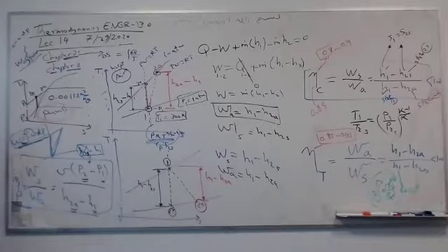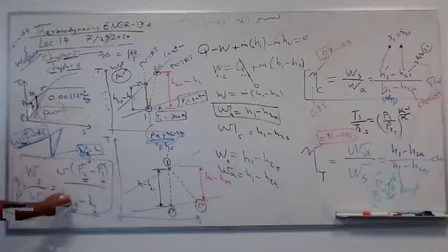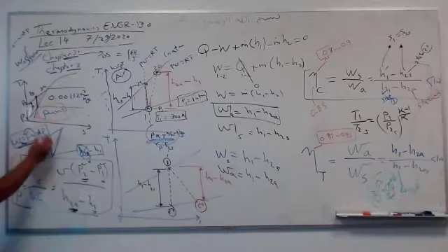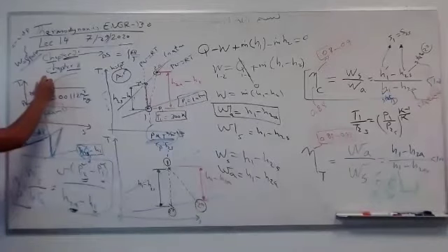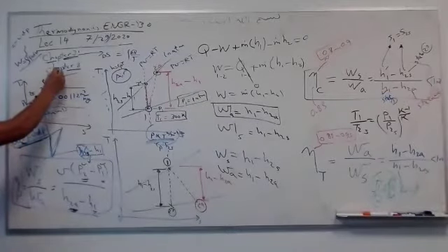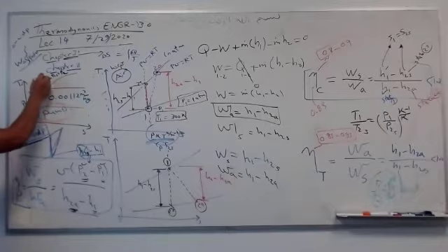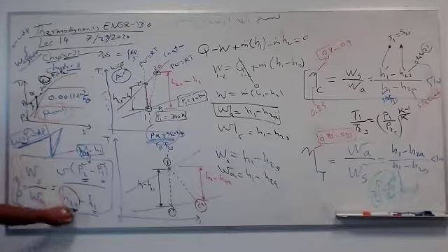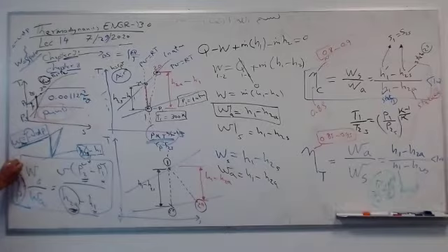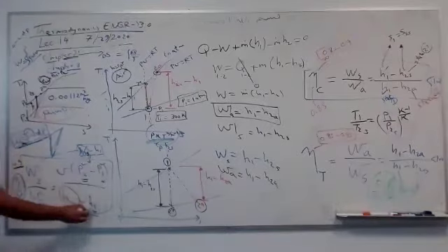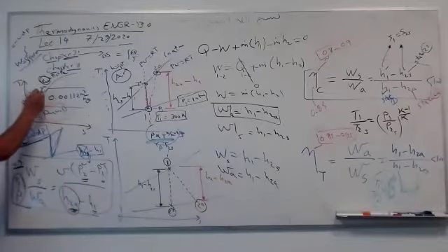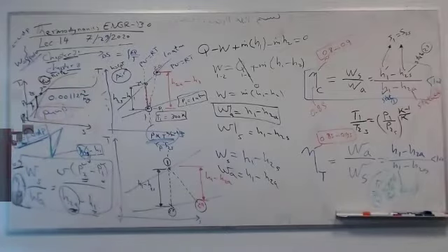So in the exam, I'll give you eta pump. You know the pressure between 1 and 2. You know, step 2A, you have just the pressure. You have just P2A, which is P2S, which is P2. So you know just P2A. We need another thing, which is this guy. Get it from eta pump. So if I give you eta pump, let's say 0.9, and you have P2, V1, H1, you can get H2A. It means you have everything at 2A. So you can continue to see what's going on. Okay?